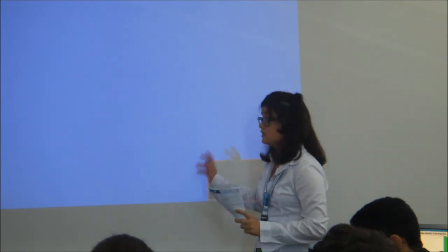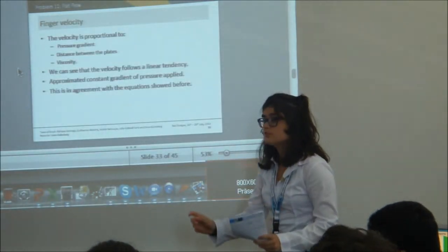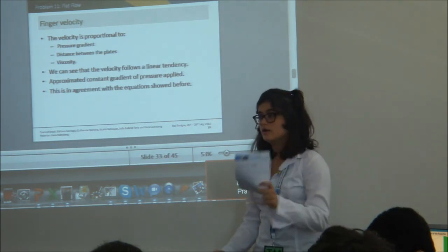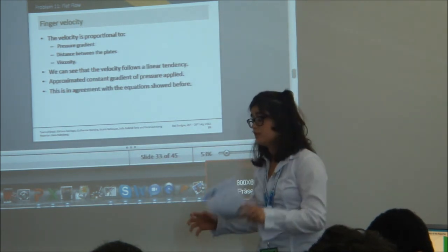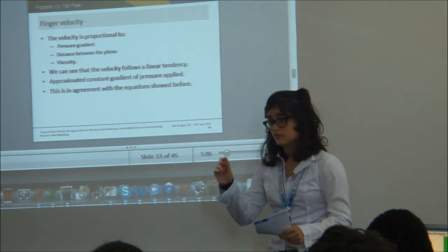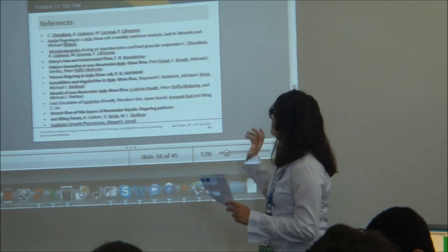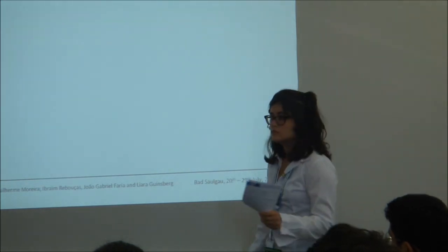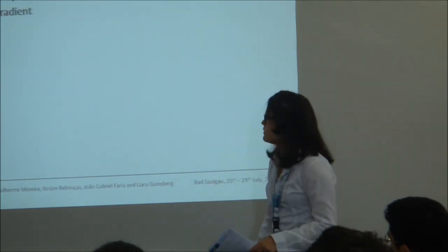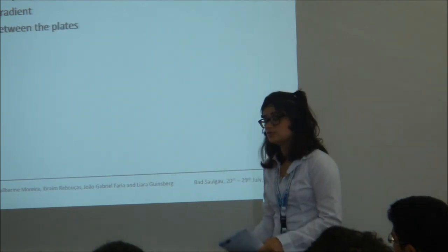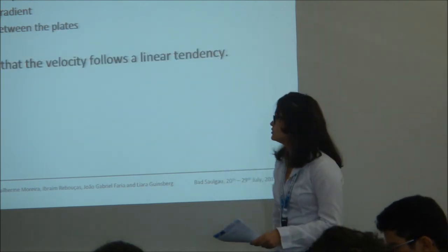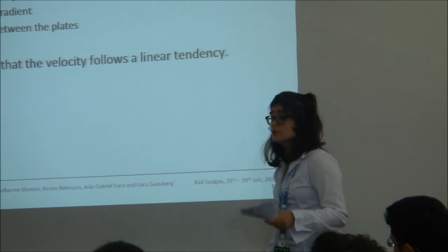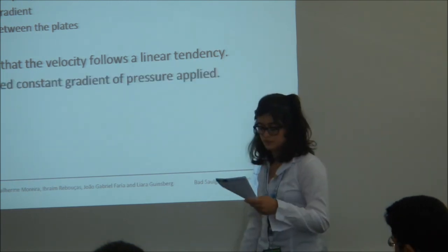I said that when a more viscous fluid is being injected, we don't have the finger pattern, and that was at a distance of 1 millimeter. This can be clearly seen in our experiment. We always have finger formation when a less viscous fluid is injected into a more viscous one, for any distance we measure.